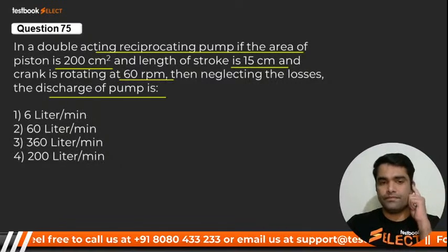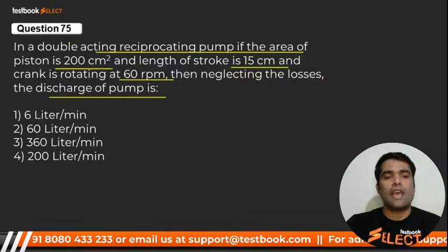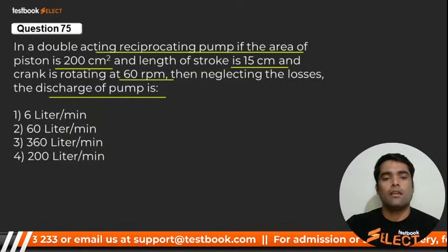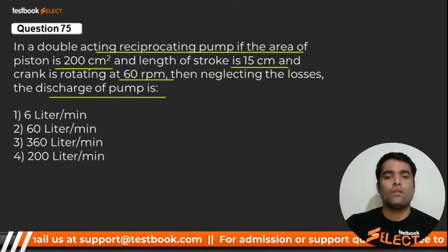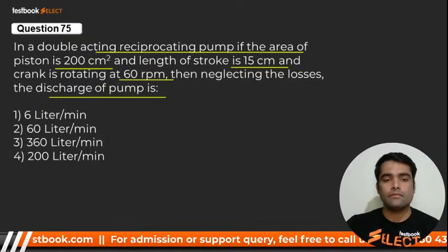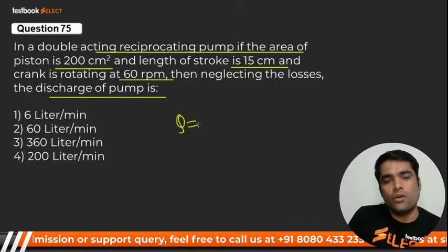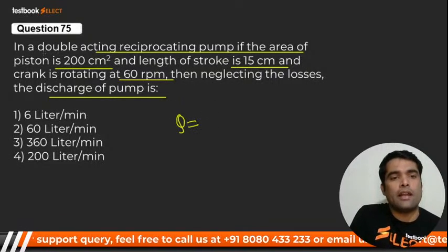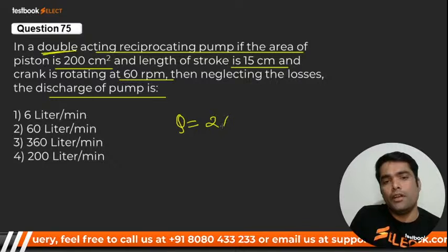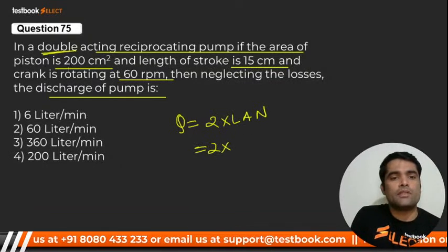The formula will remain the same. Yes or no? What will it be? L into A into N, right? Yes or no? I hope you got it. Okay. Discharge is equal to what? It is double acting, so it should be 2 into L into A into N.